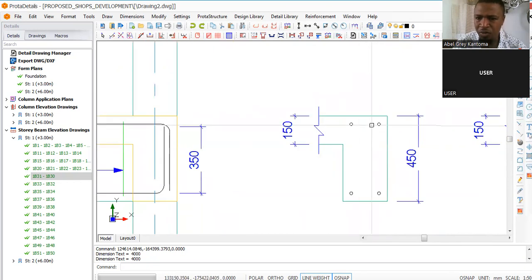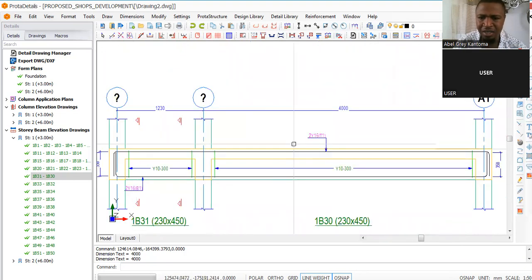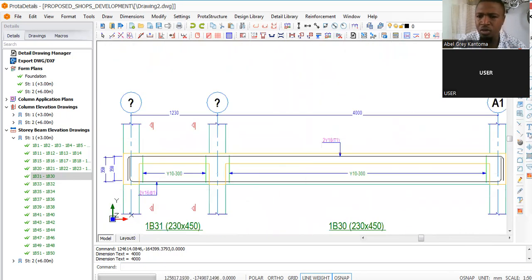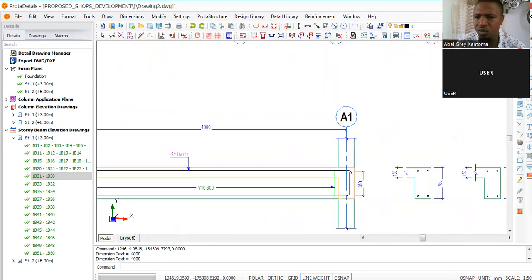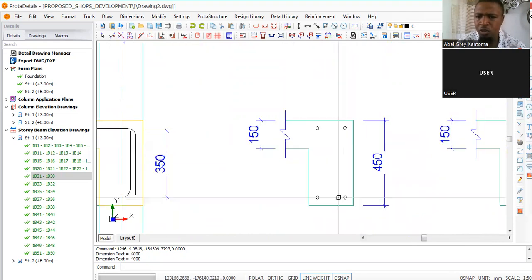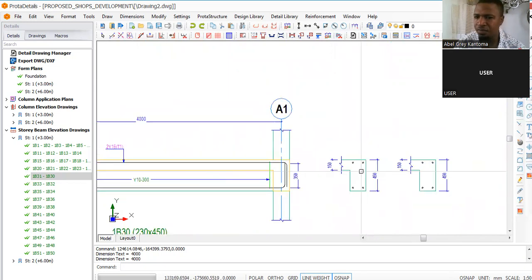And then the reinforcement you have inside, 1, 2, 3, 4, is the number of reinforcement that is provided here. Here we have 2Y16. At the bottom, we also have 2Y16. So if you add 2 plus 2, it's going to give you 4. So at the top, you have 2 reinforcement. At the bottom, you also have 2 reinforcement. So that is just it.